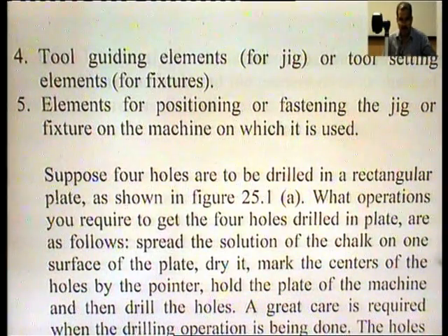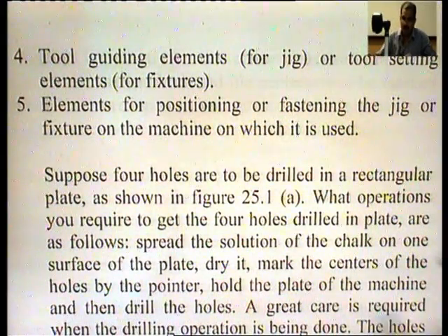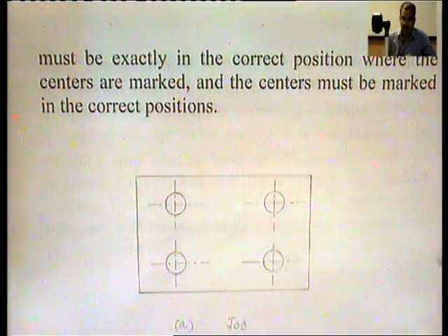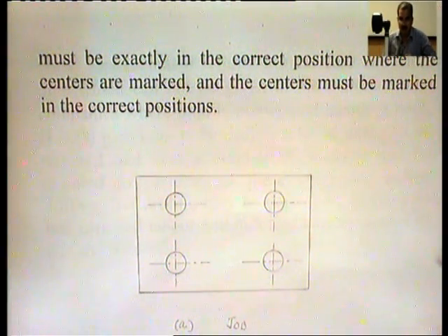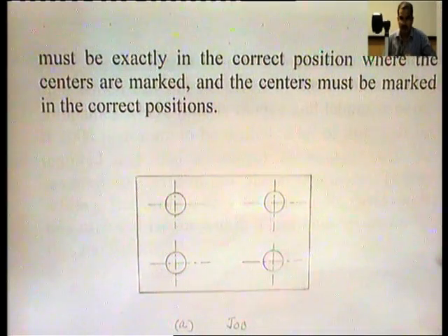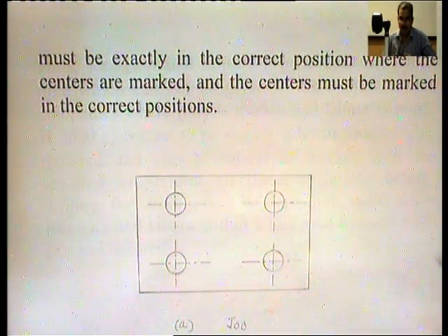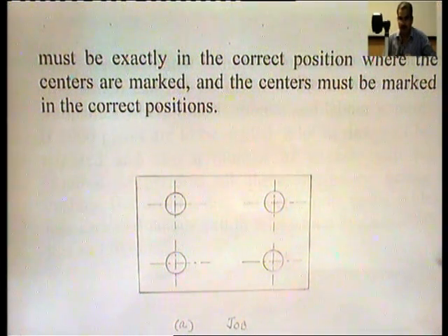A great care is required when the drilling operation is being done. The holes must be exactly in the correct position where the centers are marked, and centers must be marked in the correct position. Now, you can see on the monitor a plate is shown in which 4 holes are to be drilled.